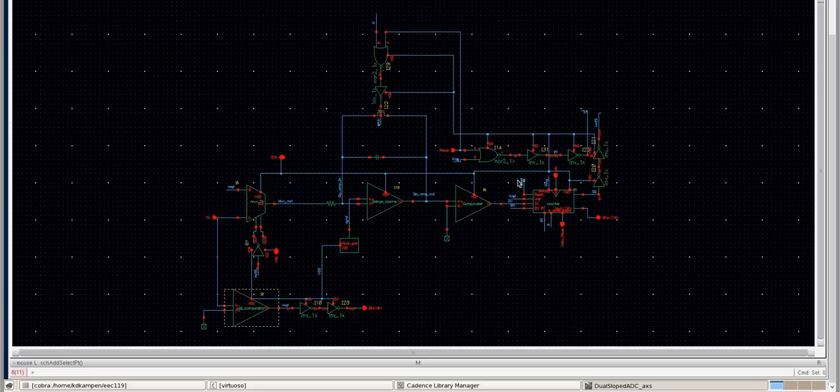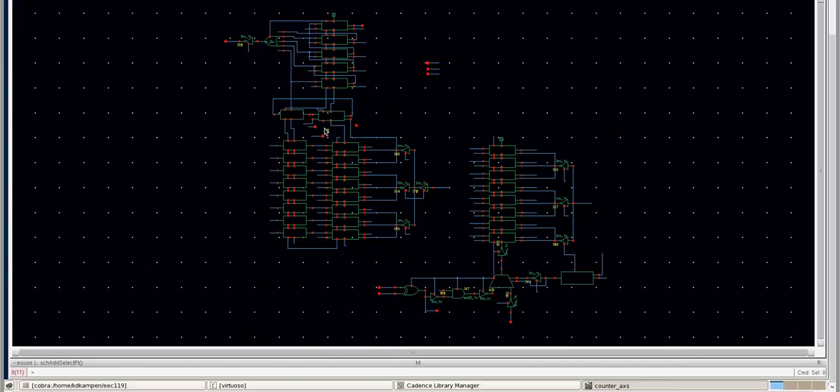This comparator is the odd comparator, which is just an odd number of inverter chains to get the opposite voltage of the input voltage. This counter logic consists of half adders and D flip-flop registers. The first set of registers just counts from 0 to 255, so 8 bits, while the second set of registers holds the actual converted data.